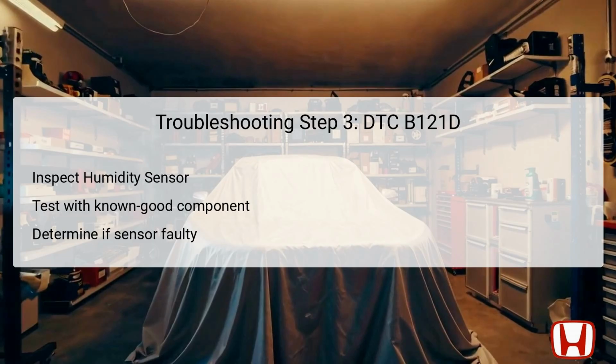In this step, the focus shifts towards the humidity/in-car temperature sensor itself. Since there is often no direct method available to test the sensor efficiently, the recommended approach is to install a known good component. This step is critical for diagnosing whether the initial sensor is indeed faulty.